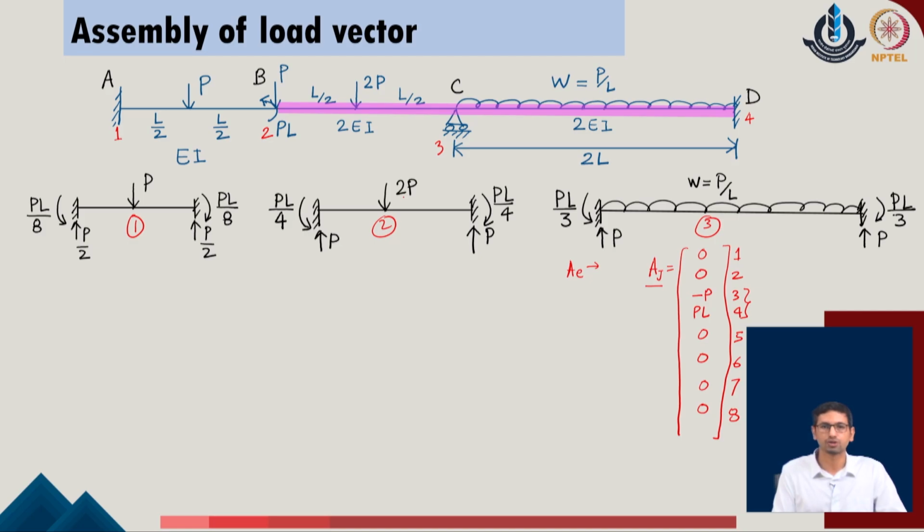To define the equivalent joint loads, we first define the equivalent member reactions in the given system, the fixed ended reaction of each of the members, and then we place them in the appropriate positions in the global assembly. Now, for member 1, we calculate the member force, the member load of the amount P, the overall length of the system is L. So, we have calculated the reactions PL by 2, P by 2 and PL upon 8 as the moment in the given system.